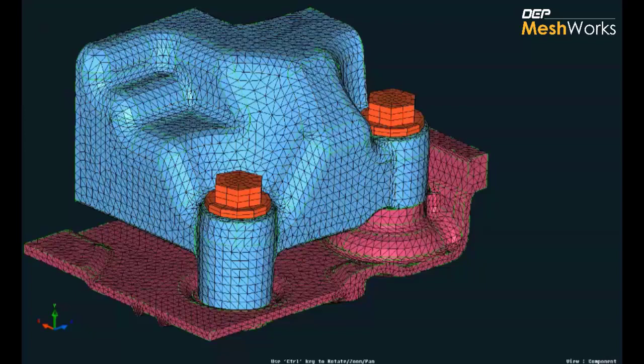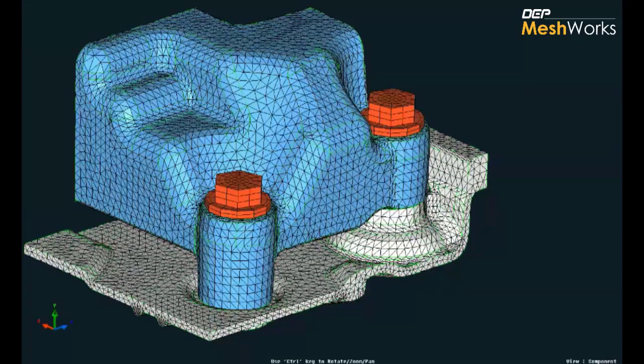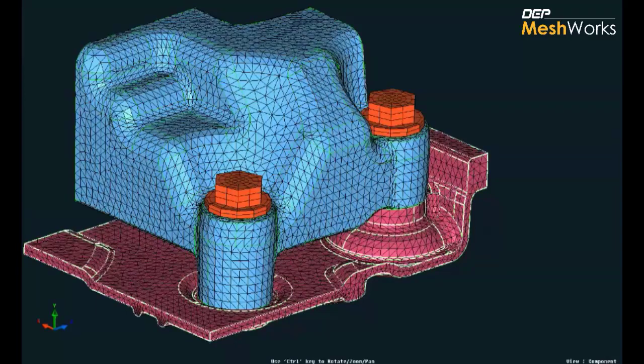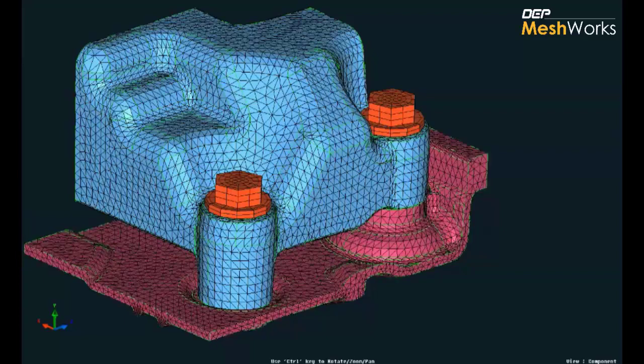The same operation I'm going to do for the other part. Here I'm going to select an FE as the current part and a CAD as a new part, and then similarly apply a meshing template and say accept. I'm just going to again modify the mesh type to tetra meshing. Once the template has been set, we can just save it and do a return. And then now we have the modeling attribute file.